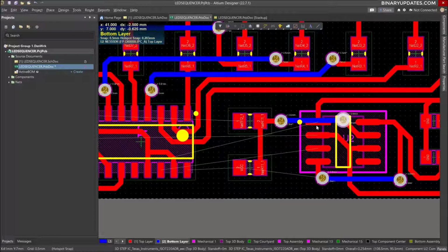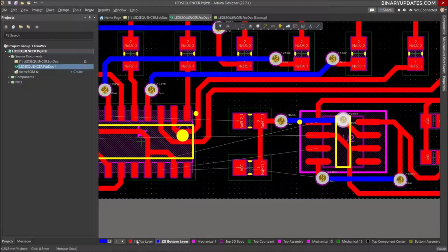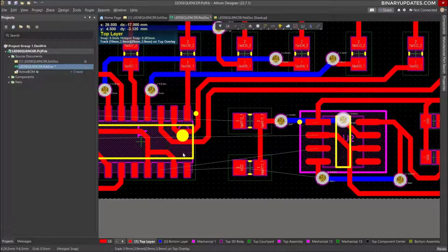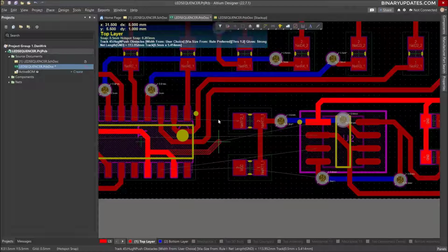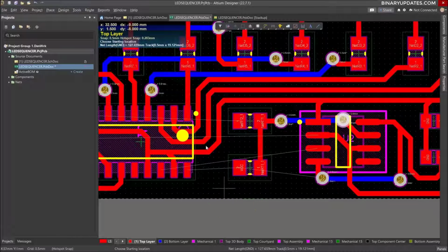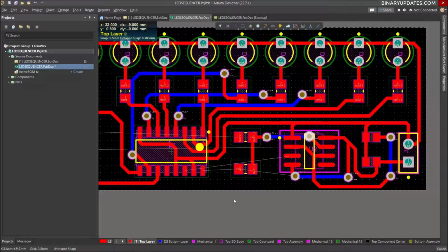Now the second pin, this one, is connecting to this one, right, which looks a little bit tricky. The second pin, which is where it's gonna go and come for the top routing. So press escape, select the top layer, Control W, and this track, I believe it should be the good choice in a long term. Okay, press escape, that's gone.